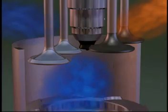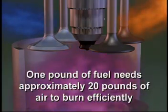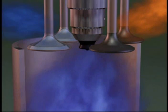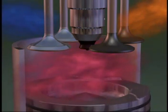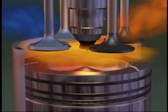The more oxygen available for combustion, the higher the combustion efficiency. 1 pound of fuel needs approximately 20 pounds of air to burn efficiently. Heat is produced during the compression stroke. As the air in the cylinder is compressed, the air molecules rub against each other, creating friction. Friction raises the temperature of the air to the point that when the fuel is injected into the cylinder, the mixture is ignited and begins to burn.